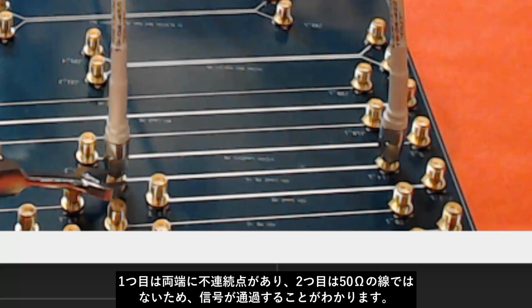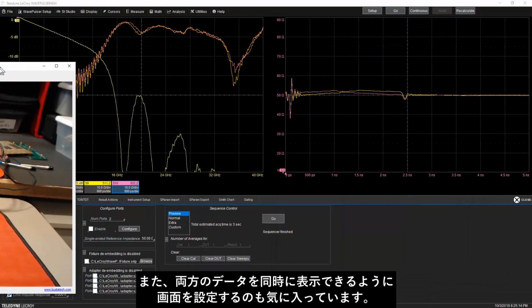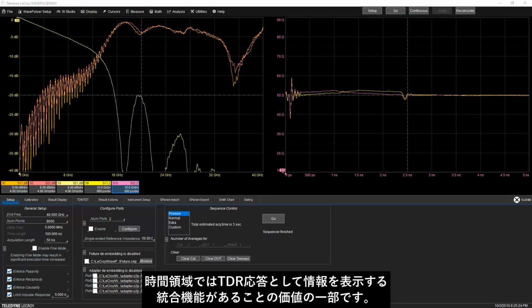And we'll see the signal coming through. We'll also display that data in the frequency domain and the time domain. And I like setting up my screen so I can see both sets of data at the same time. It's part of the value of having the integrated capability of displaying the information as S parameters in the frequency domain and in the time domain as the TDR response.